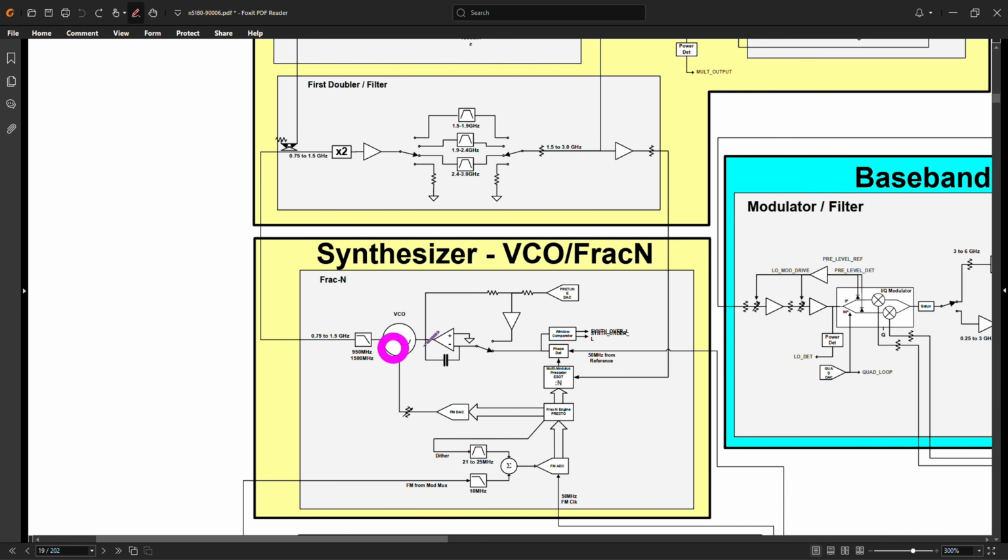So in this case, we know that this VCO and the loop works around a 2 gigahertz output, which is a 1 gigahertz VCO frequency, but once we go below that, it stops. So perhaps it just can't sustain oscillation below 1 gigahertz. And this can happen if the varactors are not working properly or something has shifted or aged.